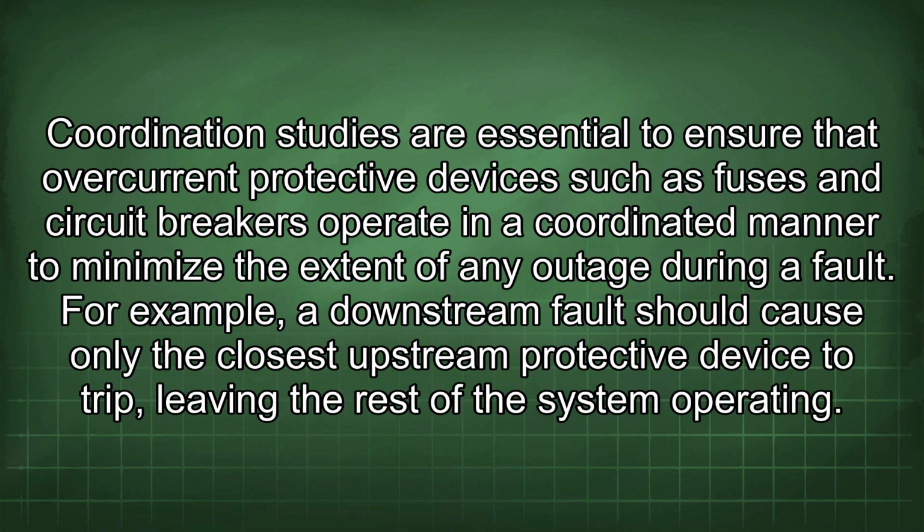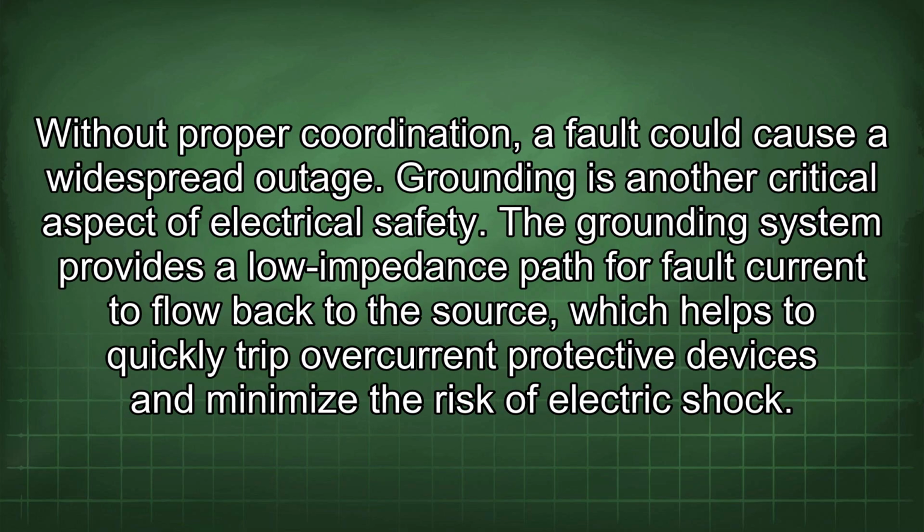Coordination studies are essential to ensure that overcurrent protective devices such as fuses and circuit breakers operate in a coordinated manner to minimize the extent of any outage during a fault. For example, a downstream fault should cause only the closest upstream protective device to trip, leaving the rest of the system operating. Without proper coordination, a fault could cause a widespread outage.